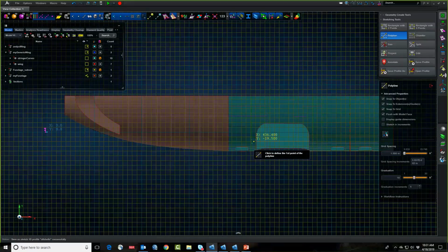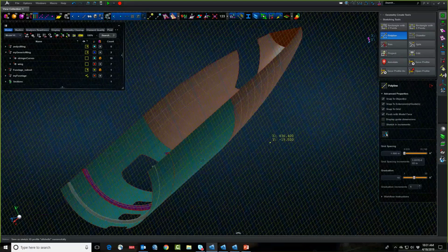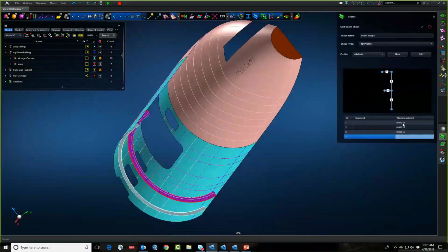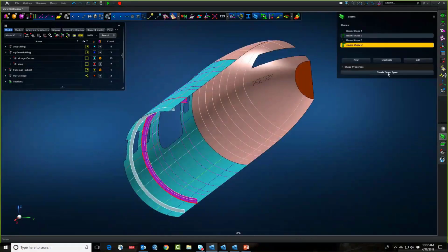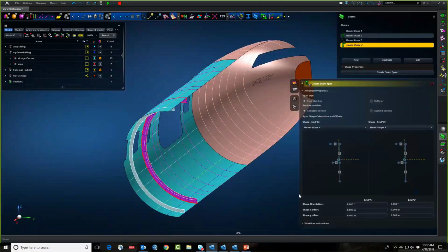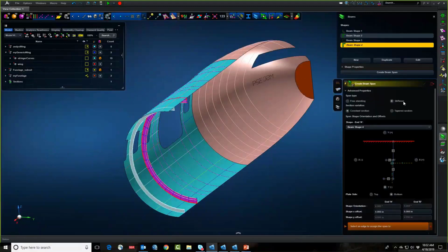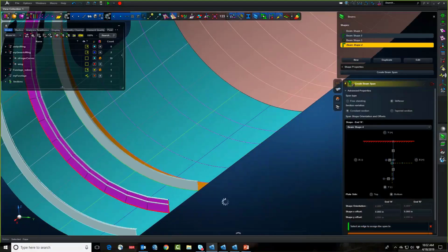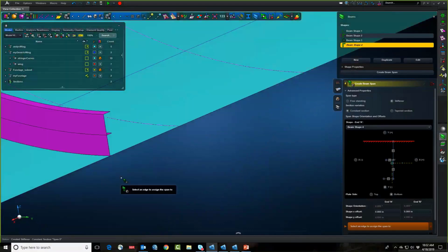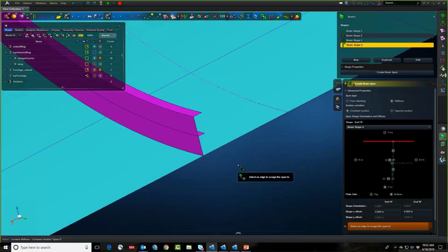And now we'll go back to my model, and I can enter in my thicknesses because this is going to be a shell. All right, and you can see that this works really well, but ultimately I really do want to automate this, right? And this is completely automatable in MSC Apex. So I will apply this as a stiffener to the existing OML, and I will simply say this curve, this surface, and Apex automatically builds for me a frame that will be a shell or shear element representation in this case.